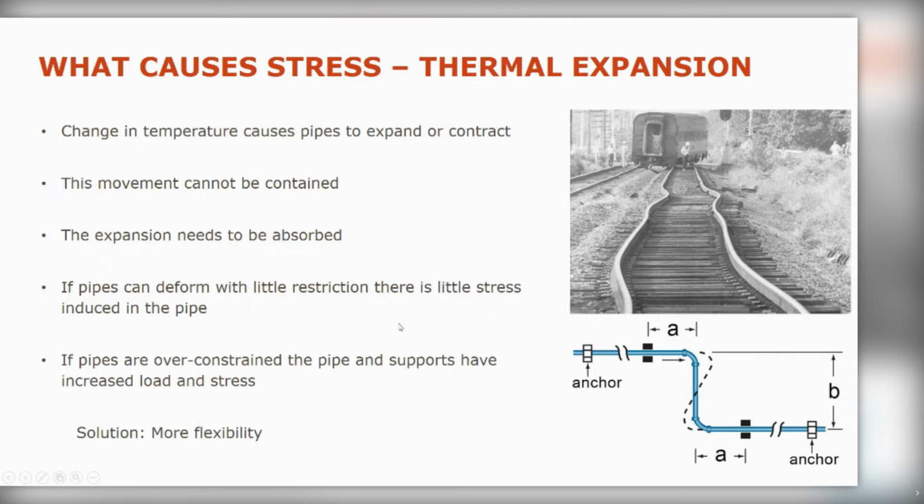So that's basically what we're trying to do. And the solution to this problem is more flexibility, i.e. fewer supports, or supports which are quite flexible, or at least flexible in a particular direction. Now, again, we're not going to go into precise solutions you can use because we don't have time, but that's something to consider. It's not just lack of supports, it's maybe supports that are clever and can allow you to absorb the motion of the thermal expansion while not over constraining yourself, but while still providing support for others.